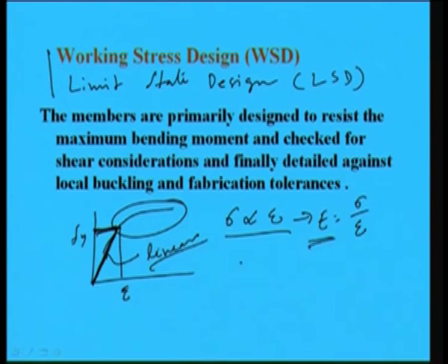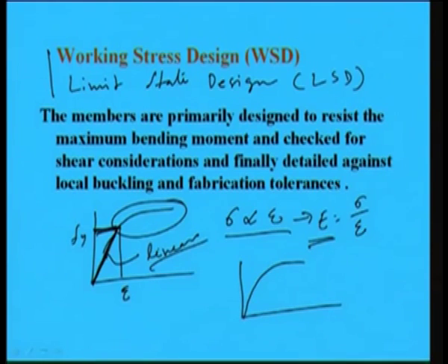But as we know, in case of limit state method of design, we are limiting in terms of ultimate load, in terms of serviceability and other things, right. Basically, what is the ultimate load method? Ultimate load method is like this, that after a certain period, if I see mild steel, the curve will be something like this and then fail. So, up to this we are going to take the effect of deflection. So, this will become f y, right. But in case of the working stress method of design, we will take up to this, right.